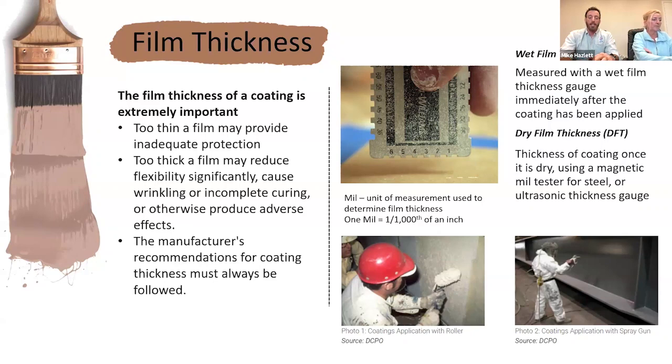And this is a huge talking point, especially with the engineers I deal with. We want to make sure that the coatings are being applied at the proper thickness. There are other ways too, if the film is already dry. Ultrasonic thickness gauges are a little more high tech, and that's not something I primarily use. We have access to one, but I use this almost daily.